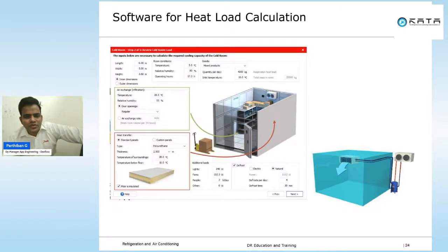Then what is the temperature you are going to maintain inside the cold storage, what RH you want, what is the pull down time, and what type of goods you are going to use. It can be mixed product, fruits, or meat. Then quantity per day: how many kg you are going to bring into the cold storage per day.